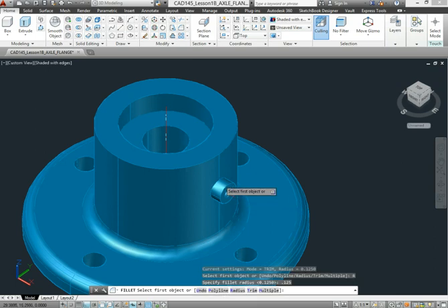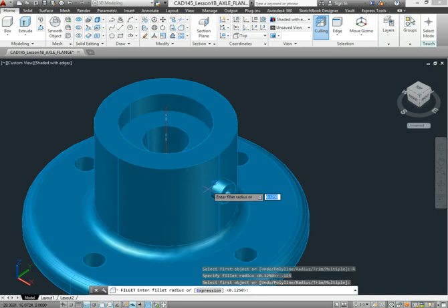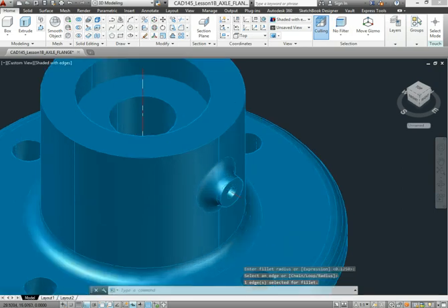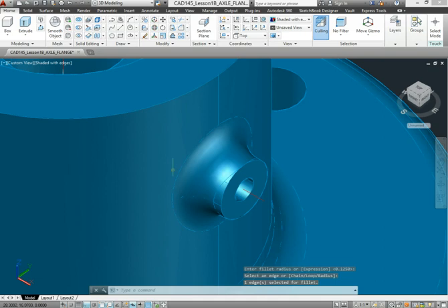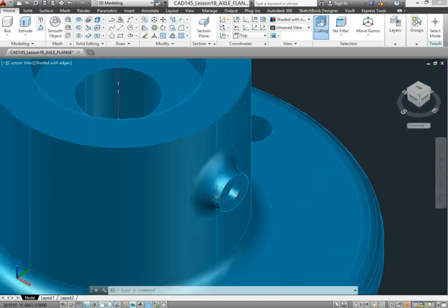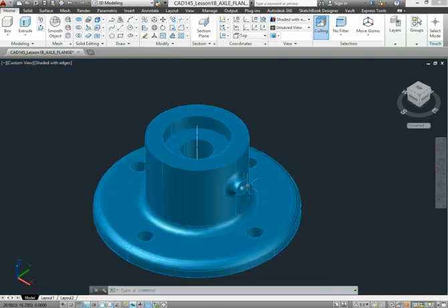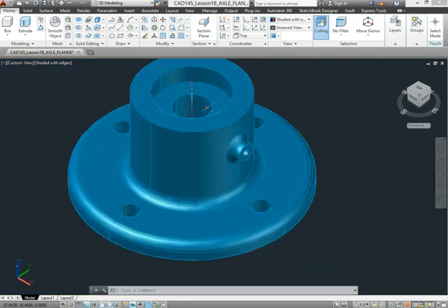And then select this edge. It found that source. Hit enter. You might have to enter twice, but there it has made a fillet that wraps around this cylinder. And it worked the way we should, as you can see those reference lines right there. And that ends that step. One last thing we need to do is we need to show the broken out section of this feature, being that we have one